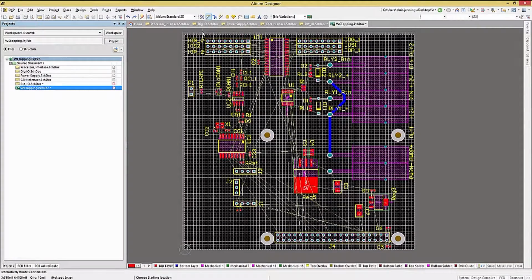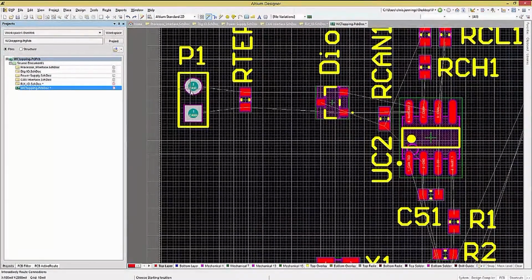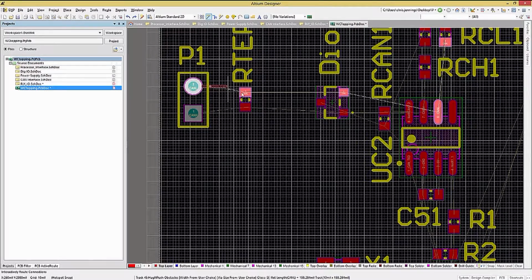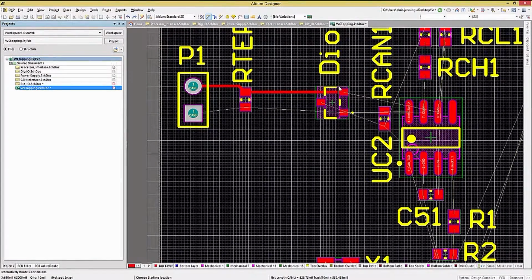As we move the mouse over the PCB, it changes to crosshairs, and the status on the bottom left of the Altium Designer tool window shows the current interactive routing connection status. Now in this mode, if we left-click on a pad, this is where we would start routing, and then move towards the endpoint indicated by the connection fly line.